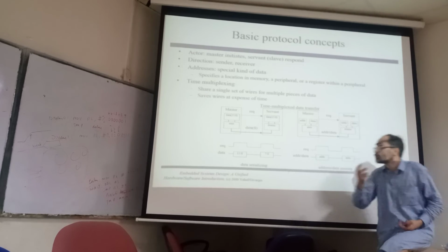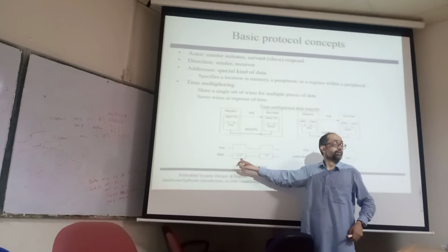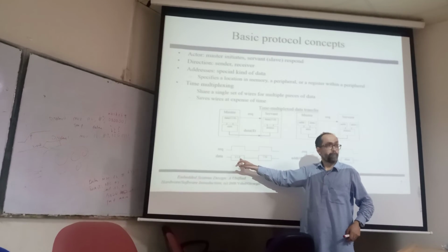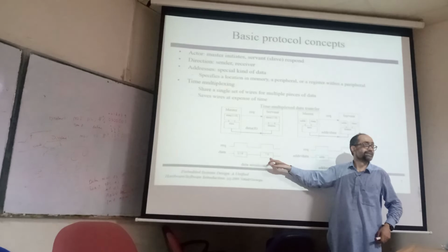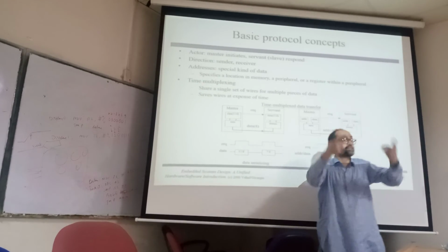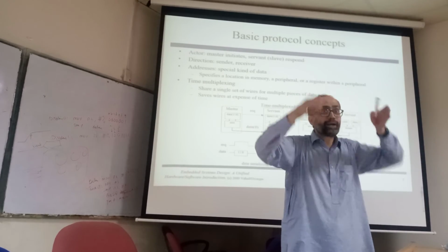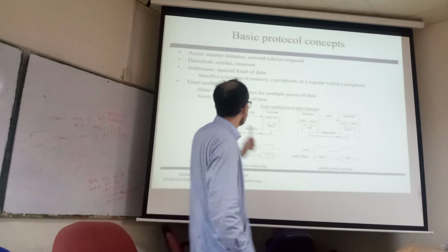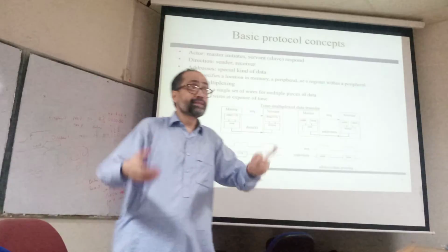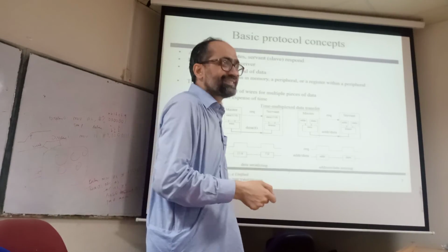2 clock cycles. So you need to send 2 requests. In the first request, you latch the most significant byte of your data, and in the second clock cycle, the least significant byte. So it requires two transactions: one transaction to get the upper byte and one transaction to get the lower byte. This time multiplexing is used when the size of the data you want to read is greater than the size of the bus.